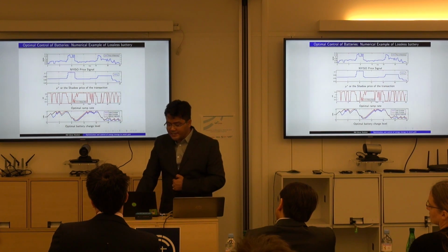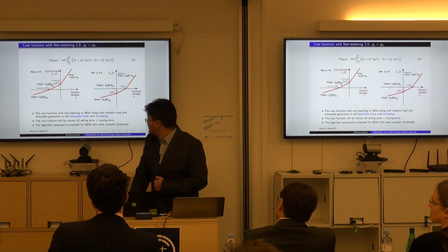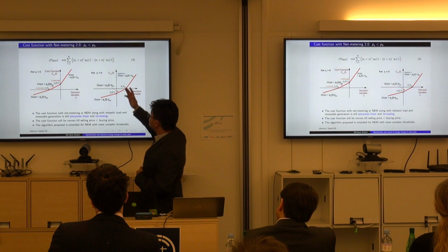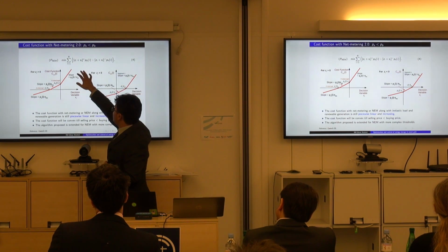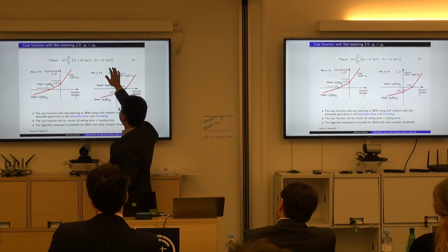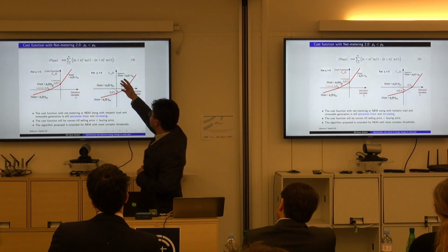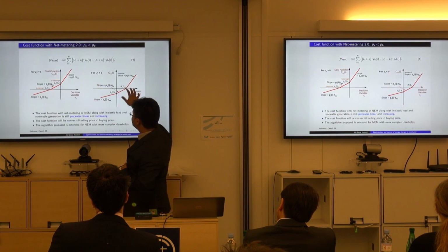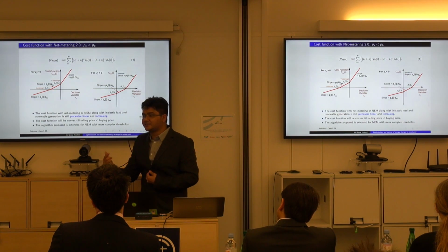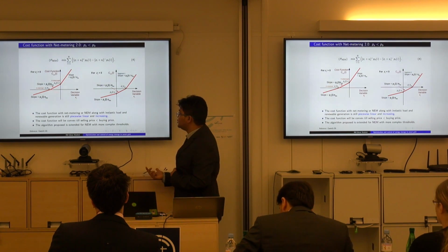So how do we extend this algorithm for net metering 2.0, because that is the most general case? It turns out the cost function still remains convex. Whenever my load is positive, I'm applying a buying price, and whenever my load is negative, I'm actually supplying power back to the grid, so I'm receiving a selling price. So the cost function is plotted based on the sign of the net load. Net load includes the consumer inelastic load minus the renewable generation.